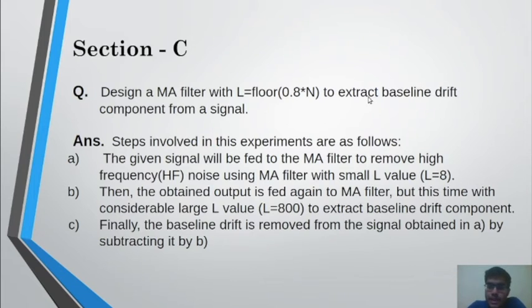It generally arises because if a sensor is attached to a moving body, or the sensor itself is moving, then there can be a drift, or a shift in the plot or in the values which we get, due to the movement of the sensor. That we need to eradicate so that we are able to get the original signal and proper information, or else we have to work with distorted information which isn't right.